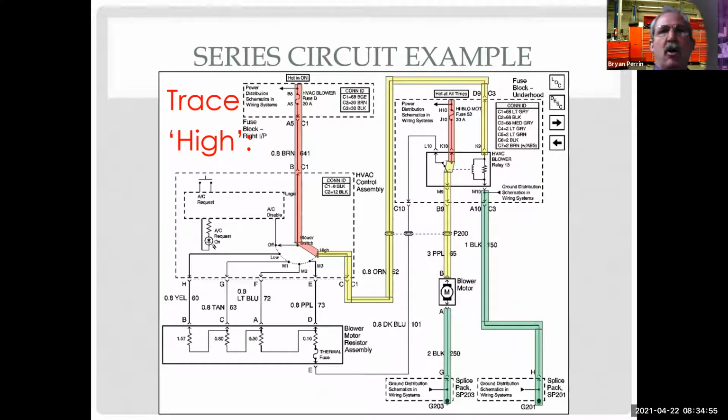So you can see where relays make great test points, because in this example I can isolate all 4 legs of the circuit at one test point, which means I only need to look up one thing, and I only need to do all my tests at one location to figure out what direction my problem is, or if the relay itself is the problem, and relays go bad all the time. So that's why I say relays make great test points.